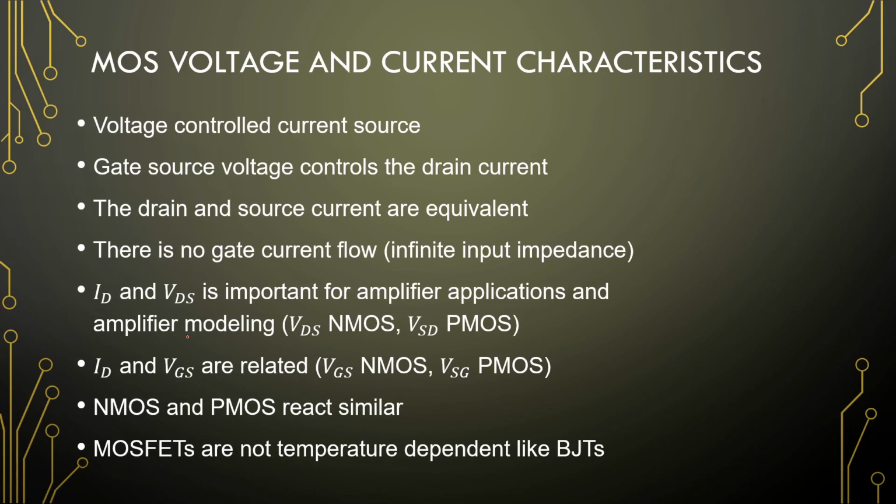And therefore we don't have any losses, in inverted commas, like we had with a BJT, where those two currents should be summed to get the emitter. Now the two are just always the same, and the gate current is truly zero, and that will make most of your mathematics very simple.